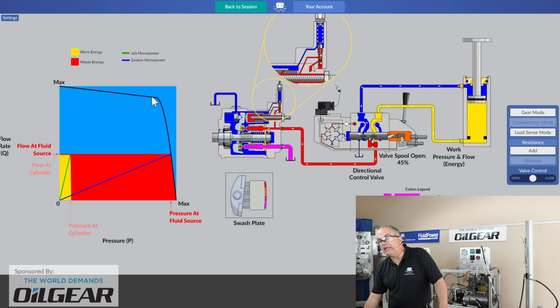If you look through the data sheets for piston pumps, you will commonly see this graph with a start of a downhill slope, letting you know how much internal leakage may happen in that pump as you come up to the corner. And at the corner here where we trigger into the pressure compensator function, it falls off much more steeply. And on this steep slope called the active region, we are now with the swash plate somewhere between minimum and maximum, moving back and forth, constantly triggering as pressure drops a little bit due to internal leakage.